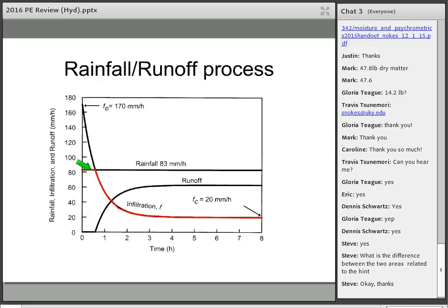So while it's up here, you've got no runoff. When rainfall starts exceeding infiltration, or conversely, infiltration rate starts getting less than the uniform rainfall, then the difference between them is the runoff. And actually they cross, and then you've got runoff as infiltration goes toward a constant, conceptually the saturated conductivity of the soil we're talking about.